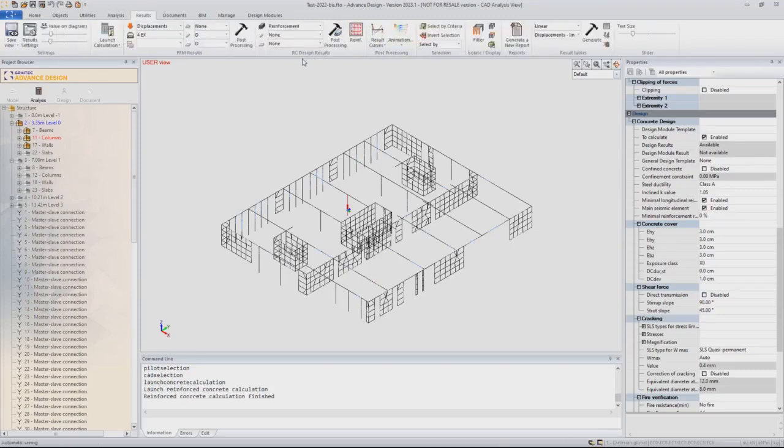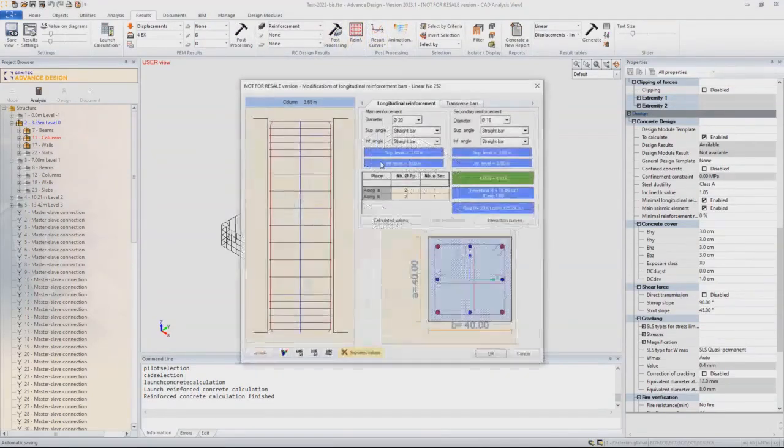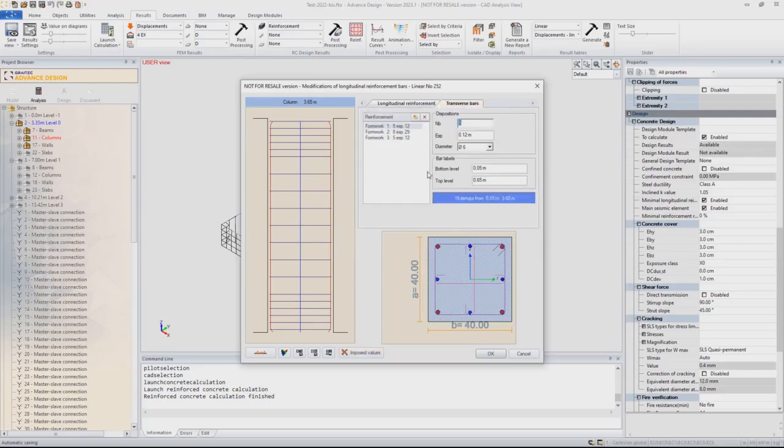And it's very quick, it's almost instant, and you get access to a reinforcement preview. You know which longitudinal bars you need, so I need a mix of 20 millimeter bars, the red dots in the corners, mixed with 16 millimeter bars along the sides. I get the same information for transverse bars. I know the diameter and their spacing, but that's pretty much the only information I have.